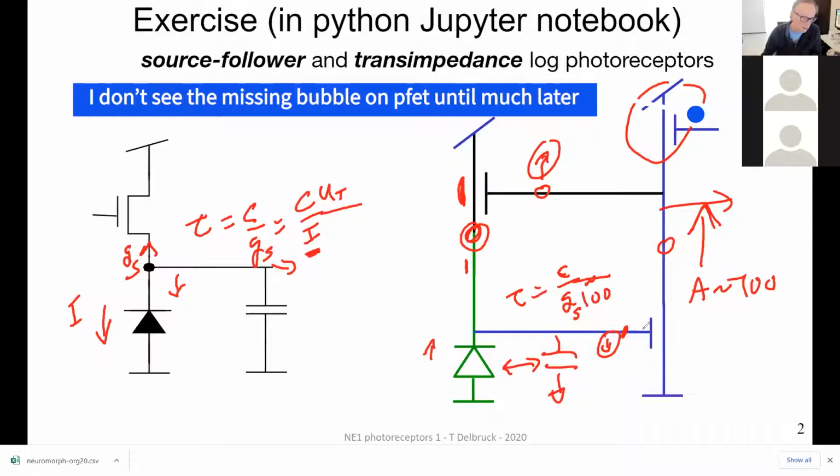Okay. Now there's something I'm not telling you about, and I'm not going to say much more about it in this lecture. At least I'll say more about it possibly next week. But you have to realize that there is something I'm leaving out of the story, and I'll give you a hint to it. What if you have a parasitic capacitance here and here, and you do have those parasitic capacitances because they're the gate to drain or gate to source overlap capacitances. They're physically this little overlap here between the gate and the drain, those little yellow capacitors. What happens if you have those? Get multiplied. Yeah.